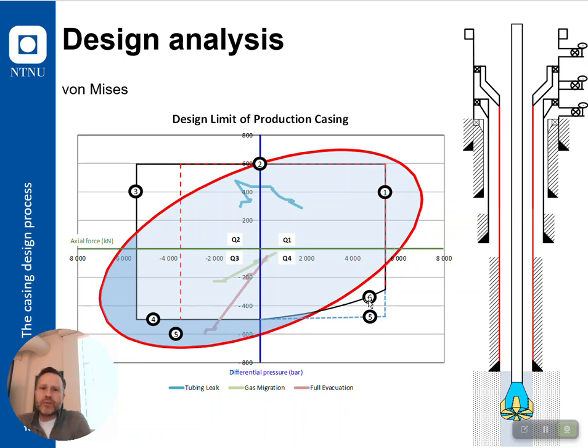Line number 6, that's where we have the correction of actual tension for collapse for the API collapse calculations. Number 5, that's where we have elastic collapse. Remember that elastic collapse does not correct for yield strength. It doesn't look at strength whatsoever.